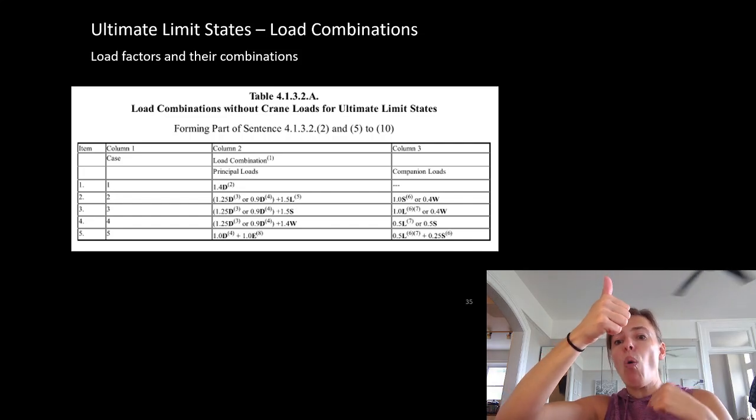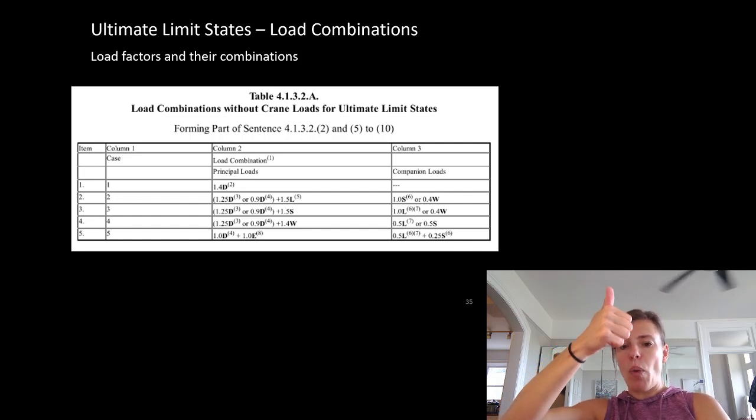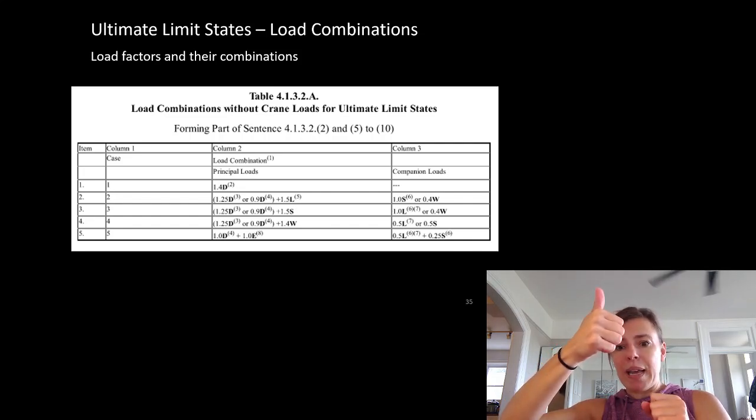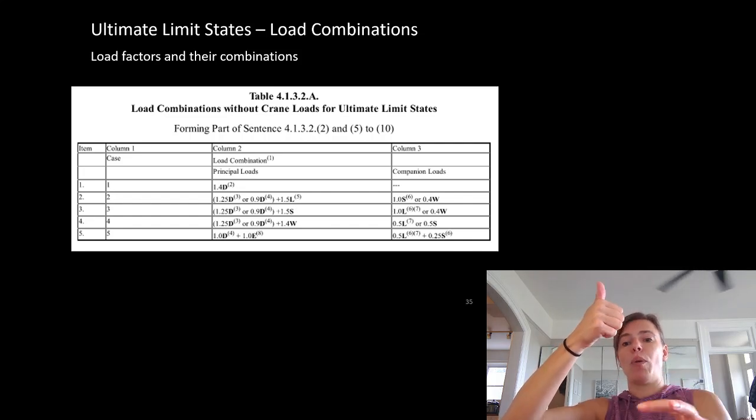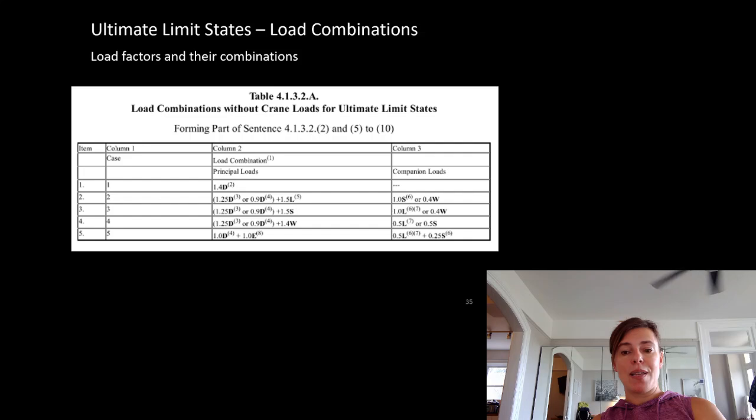What if we overestimated the weight of our dead load? We want to consider that we might have overestimated, so the other direction, and say, okay, now we have to apply a factor of 0.9. So in that case, it would be 0.9 dead load acting downward and 1.4 wind load acting upward.